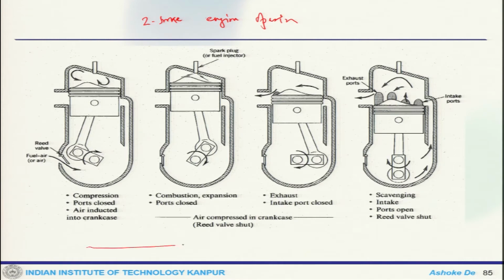When the inlet ports are uncovered, fresh charge which has been compressed in the crankcase flows into the cylinder. That is how this process continues.